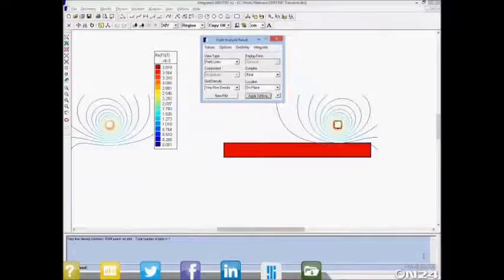When you have time-dependent sources, such as AC voltage or current source, then you will see the magnetic fields generating an electric field, which in turn will induce currents in any nearby conductors. And in a simple harmonic case shown here, what we have is a disk of copper. This is a rotational model, so the copper actually revolves around to create a disk over on the other side.